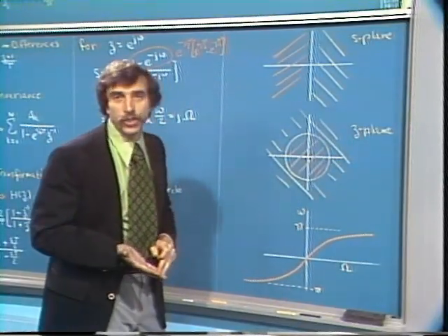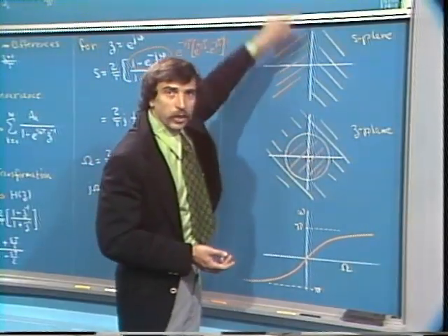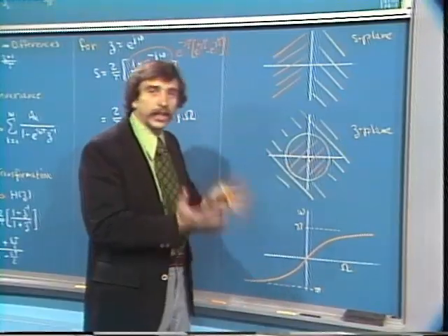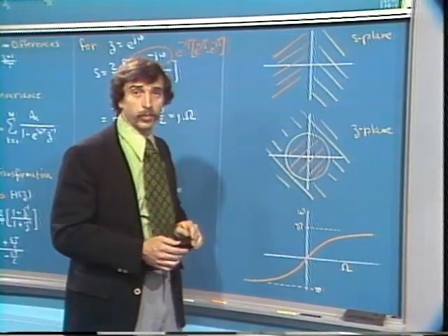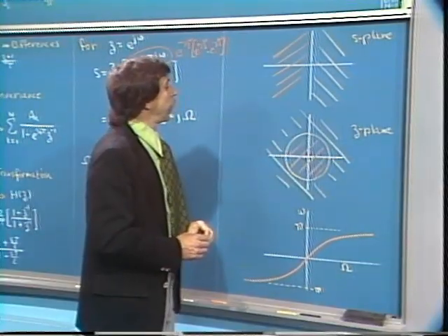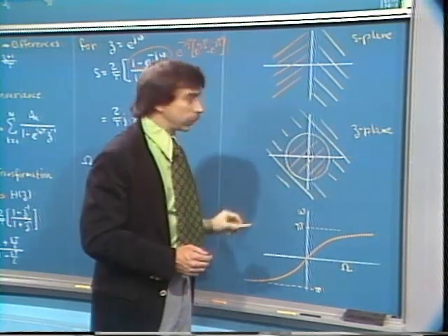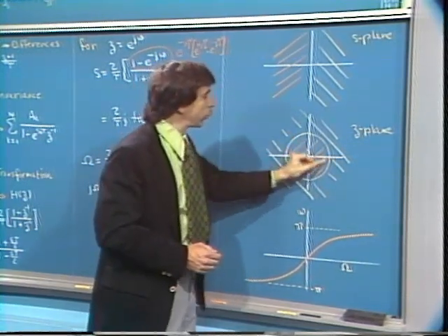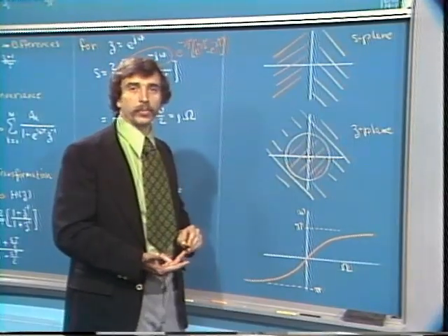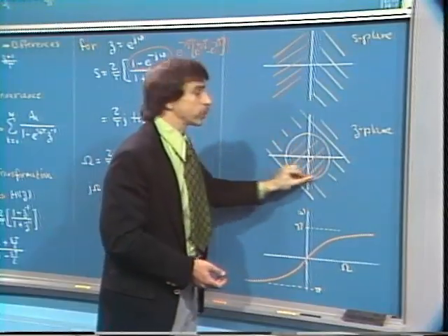One is that obviously there's no aliasing involved anymore because the entire j omega axis ended up once around the unit circle. That is, there was nothing that got added onto something else that got added onto something else, as it did with the impulse invariant method. The second point is that that axis is infinitely long. The unit circle only has a finite circumference. So clearly, something has to happen. Something has to be distorted in order to fit all of that onto just this little bit.